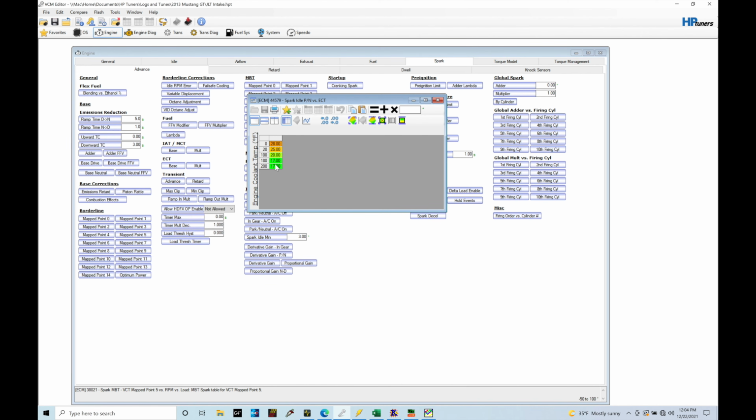Now we're going to notice a trend here. We see at the colder coolant temperatures versus the warmer coolant temperatures, the spark timing in the table is completely different. At the colder coolant temperatures, we command more spark advance because we have frictional drag from a thicker viscosity of the oil on the engine. We also have the factor of a wall wetting type of situation going on, where the fuel isn't getting to the engine as efficiently as possible as we're spraying the fuel from the injector into the intake manifold, going through the intake ports. It likes to stick to the intake valve and the intake port.